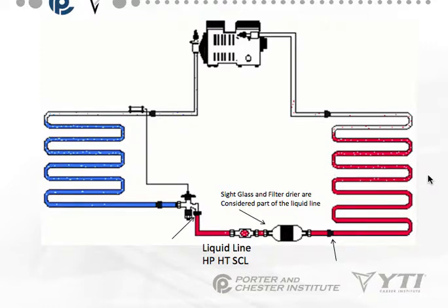Let's say my condensing point is 30 to 35 degrees above the ambient temperature around it, which is typical for refrigeration. My liquid line is subcooled, and it's going to be under that condensing point. We've removed more sensible heat, and that's normal. You want that.